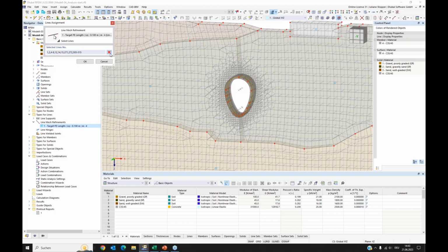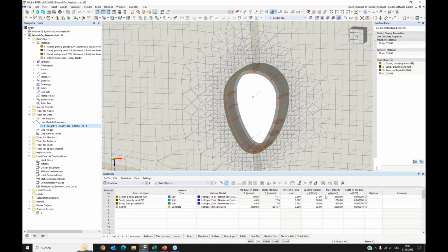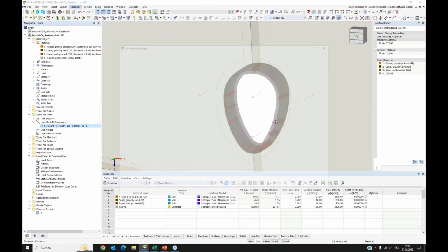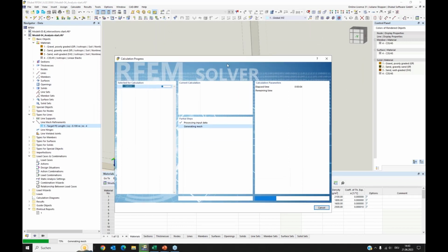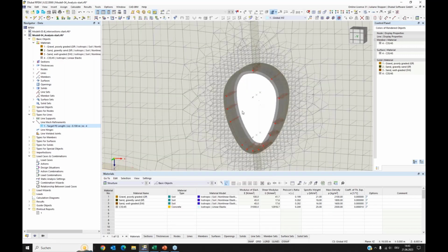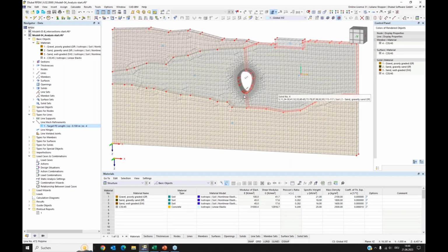We can remove it. I only wanted actually to assign these lines because it's something nice. The layered mesh automatically extrudes it into the depth, so it's not needed in the next step to again assign the lines. With this one line it's done. You can see. Okay, so we have this. Then all of the topology is prepared.